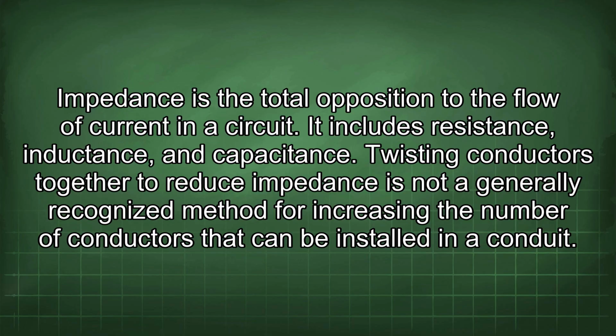It includes resistance, inductance, and capacitance. Twisting conductors together to reduce impedance is not a generally recognized method for increasing the number of conductors that can be installed in a conduit.